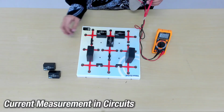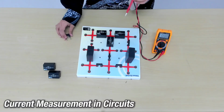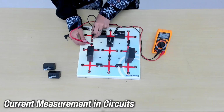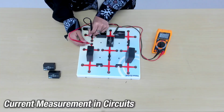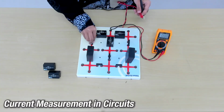Okay, do not forget to retake the connector. Next, to measure the current in loop 2, unplug one of the connectors. Then insert the probe into the connector hole that was just removed. Okay, record the current reading and remember to retake the connector.